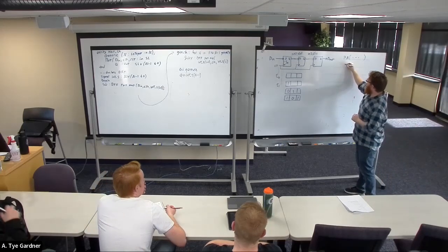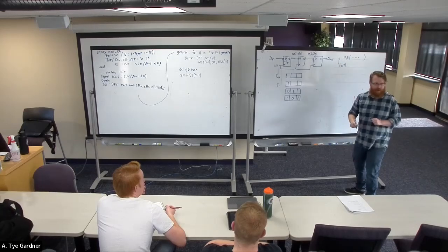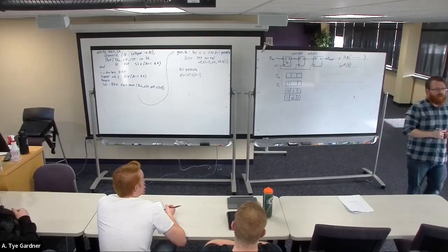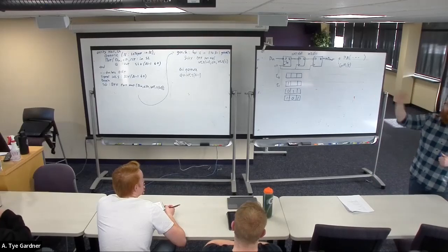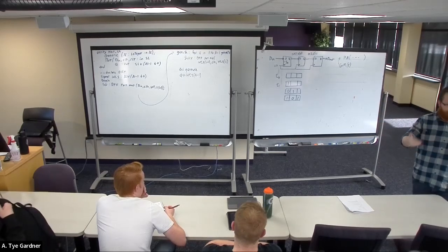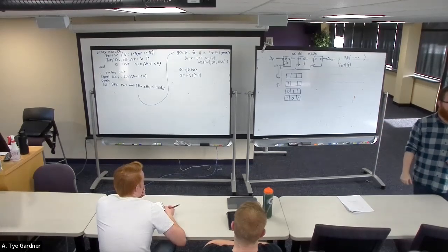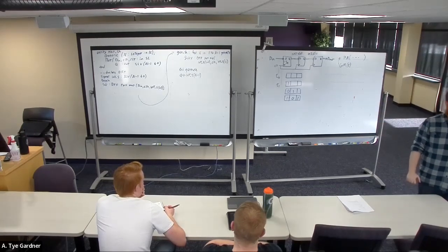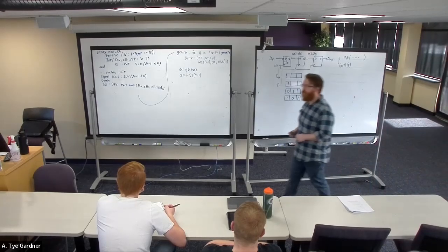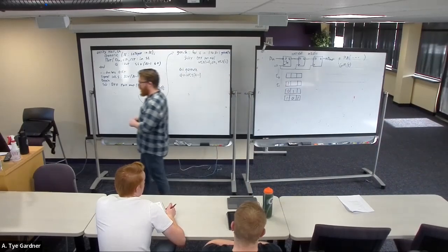However, I can instead add before that a generic map, 8. Now it's 8. So the default value says I don't have to declare the generic map. I can just let it go if it's the size that I want it to be.